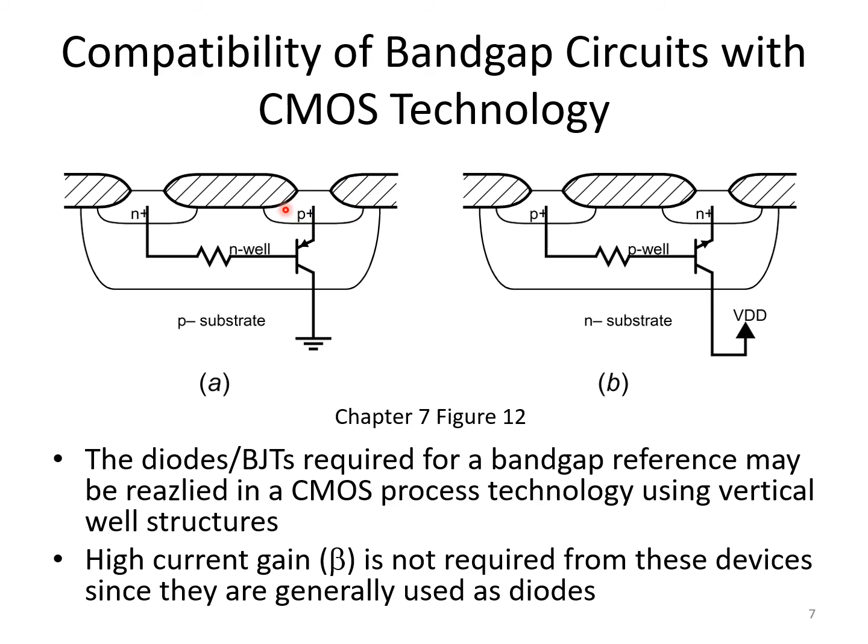We just make use of it as a P-type region inside of an N-well, and then with the P-type substrate underneath, we've got a sort of PNP structure that we can use as a BJT. Now, since we're just going to ultimately diode connect this BJT, we're going to short together the N-type base with the P-type emitter. We're really just using it as a diode in any case.